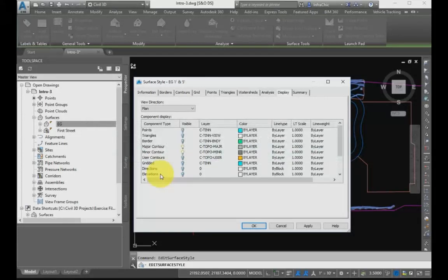As your data changes in Civil 3D, so will the objects associated with that data. Depending on the style assigned, you may or may not see the change to your object right away. If you've set the style to no display or boundary only and the data changes, the objects with that style that are affected would not visibly change.